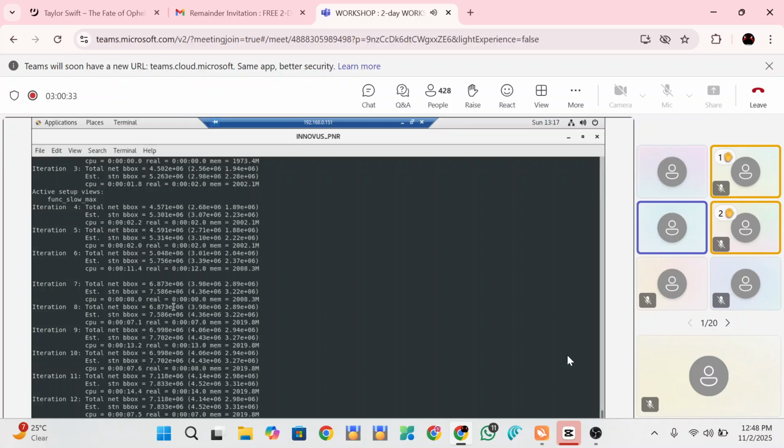Okay, can you show how the different concepts happen? Based on the gates, everything will be placed like a top view. If we are looking at the top view now, you see the red color one model, blue color different one. These are the gates. This is the flop, this is the flops. How they are placed is like if you look at them side by side, they will be interconnected with the routing. The placement is standard set itself. You don't have any overlap. Everything is properly aligned in the rows. So you have to check whether the check is passing with any overlaps or not.